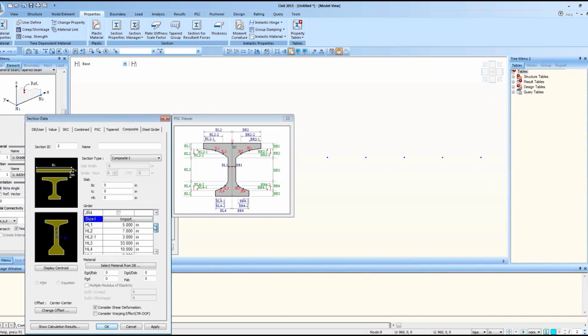And you can see the numbers are punched on here. Now let's define the effective width of the deck. So effective width is 110 inch and the thickness of the deck is 8.5 and haunch height is 0.